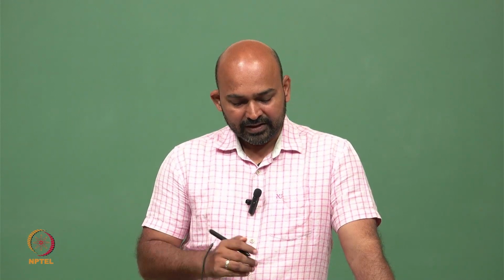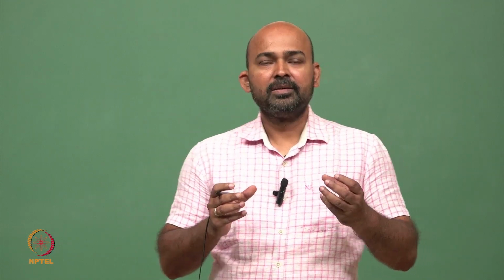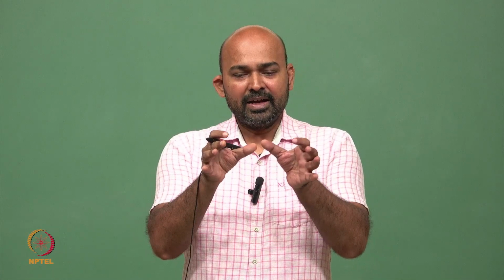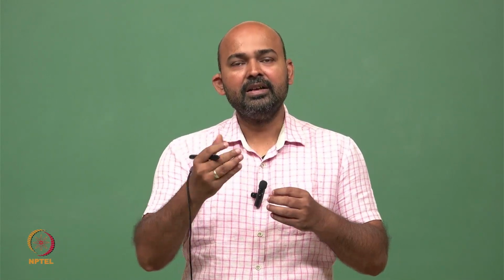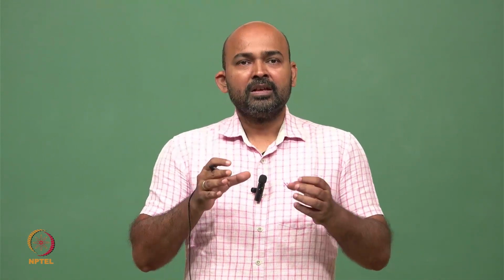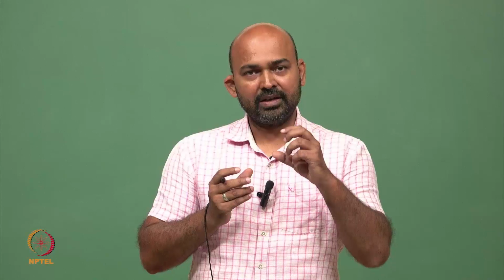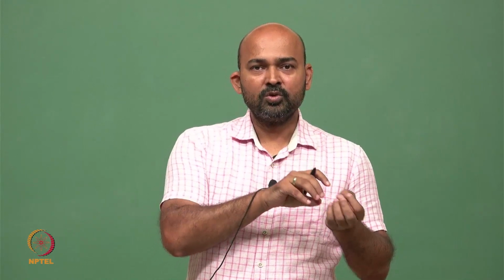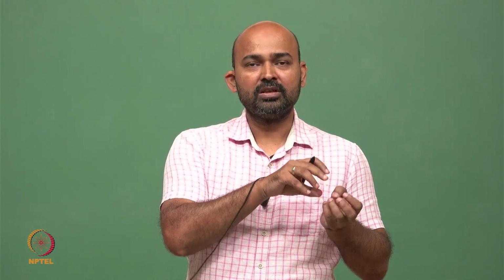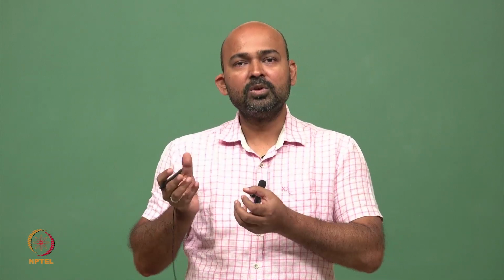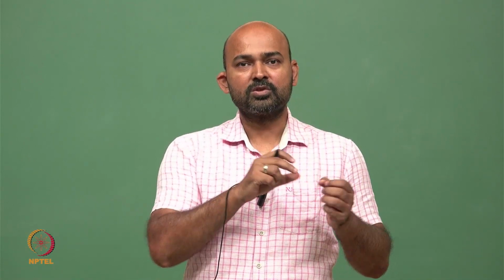function of the antenna. The second is, when an RFID tag passes through the close proximity of an antenna, the antenna has a certain area where it can radiate the energy. As soon as the RFID tag passes through that area, the energy will be given to the RFID tag, and the RFID tag detects this energy using an inbuilt antenna, which may be a smaller antenna, and this energy is now used to communicate this information stored in the RFID tag to the receiver. So this energy is sent back to the receiver with the particular information which is stored in the RFID tag.